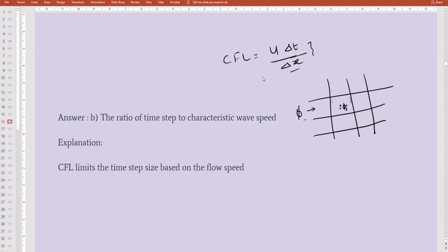So we have to fix some CFL value. It is called the Courant number, and the criterion is known as the Courant-Friedrichs-Lewy criterion. We set particular Courant numbers to attain stability in a particular scheme. I think in the fifth week's lectures, the last video discusses Courant numbers.